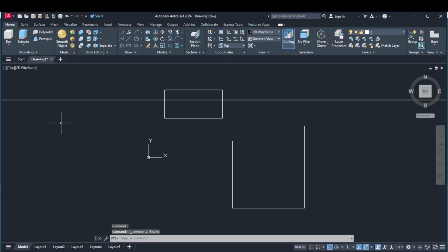So we go to another object here known as the OSNAP. We have object snap or OSNAP. What is the function of that? It helps you to snap precisely, or to specify specific points on existing geometry, such as end points, midpoint of something.